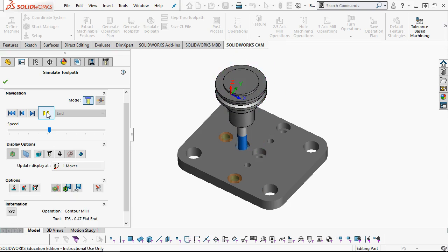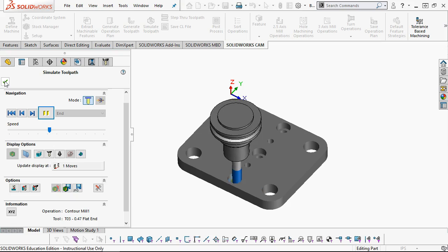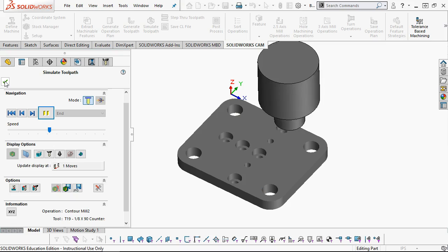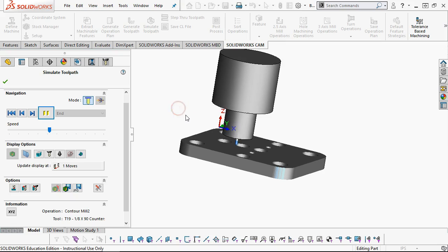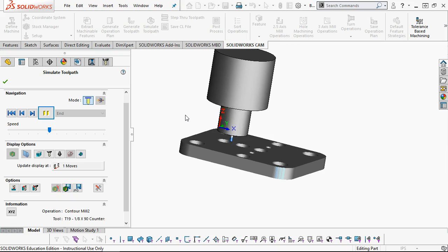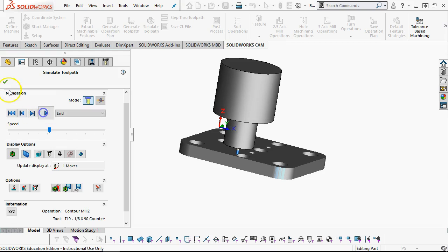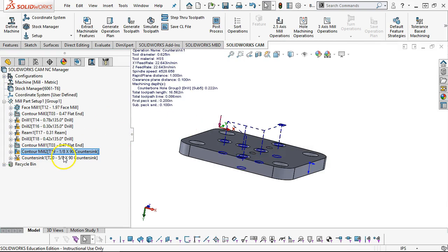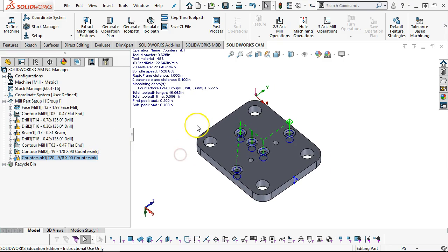And then the counterbores opening up for the socket cap screws. And not sure which one that is. That looks like a deburr operation. All right, so it's taking the 90-degree tool and it's cleaning up the edges. All right, not sure I want to watch all of those. Yeah, sure did. It picked up a countersink, an 1/8 inch countersink, no less, to clean those up.